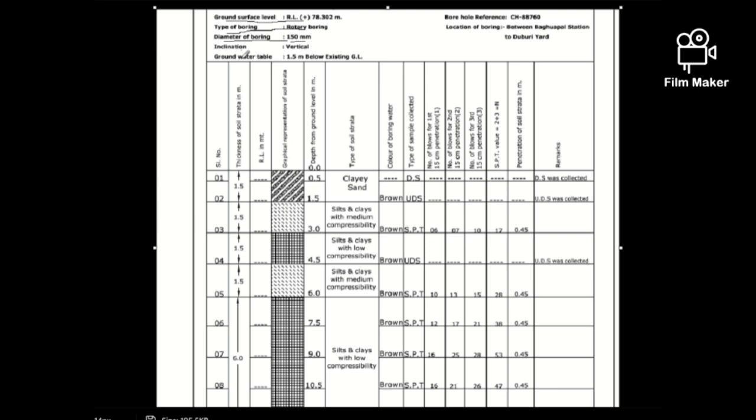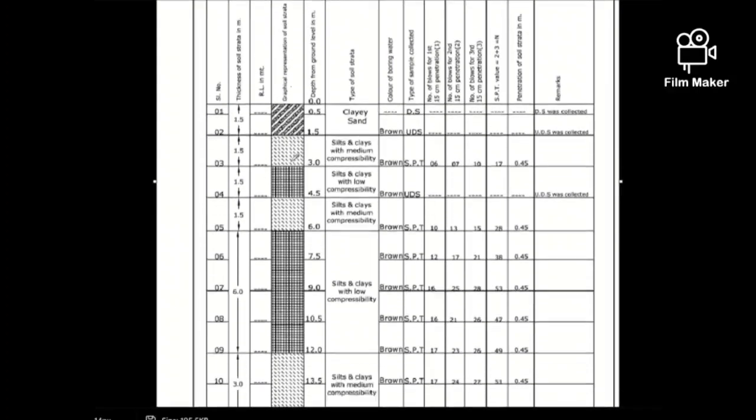hole, and the inclination, whether it is a vertical borehole, the reference, the change of the location of the borehole. And here we also have to measure the groundwater table from the ground level, because we have to measure the corrected SPT value. Here is how to prepare this chart.